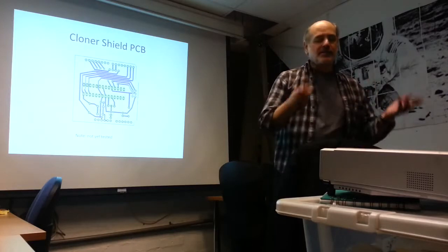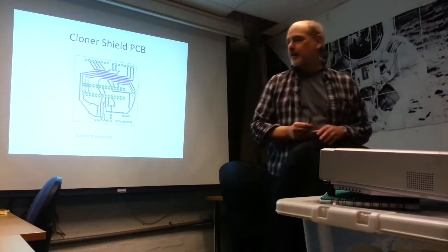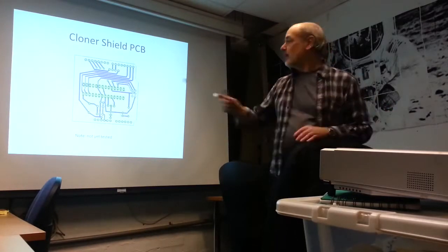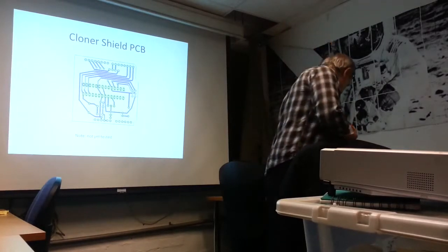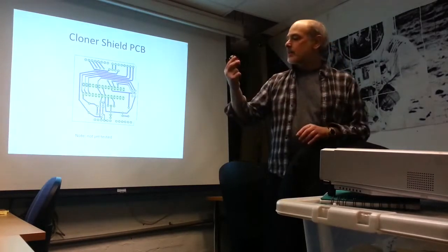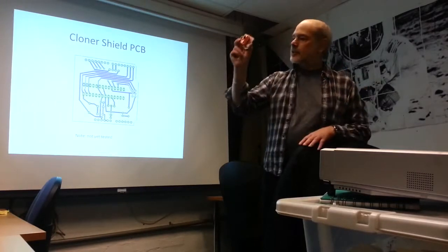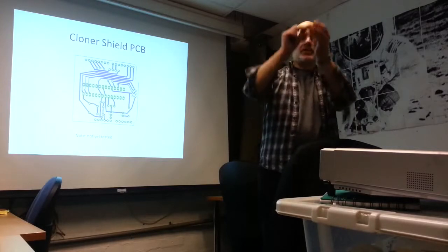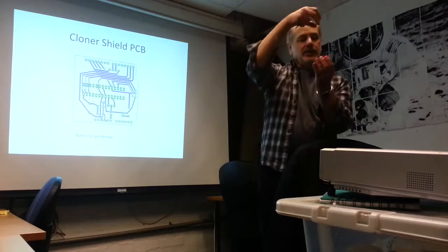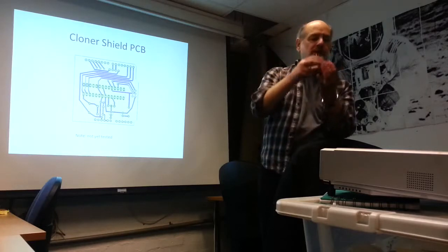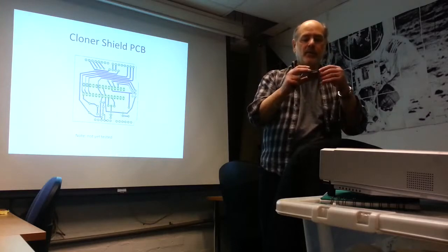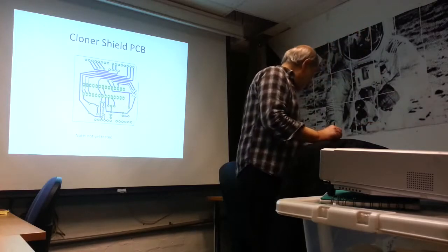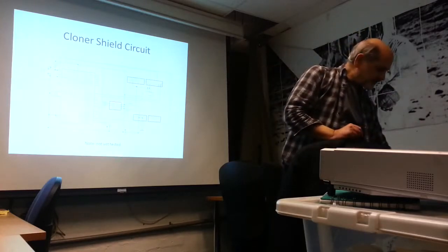Because I've been given access to a new precision miller, which makes printed circuit boards, and I need some test stuff, I decided, well, why not design a shield that does this? So I took the circuit and turned it into a shield. So this is a similar circuit. What this does is it plugs into a standard Arduino. The slave chip that you want to program plugs into the top, and then running exactly the same software, it will, in about 10 or 15 seconds, burn the bootloader and run the test. So that's the circuit board.